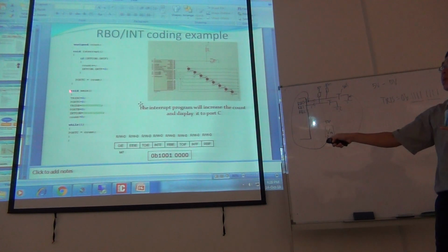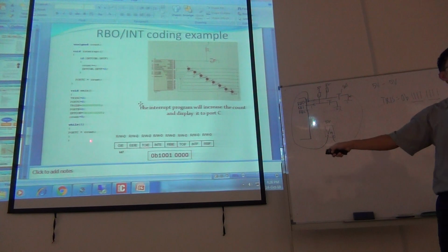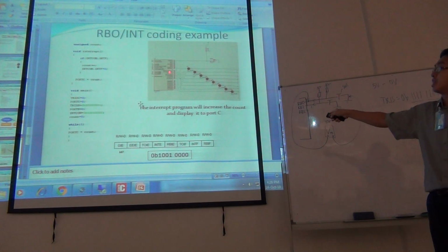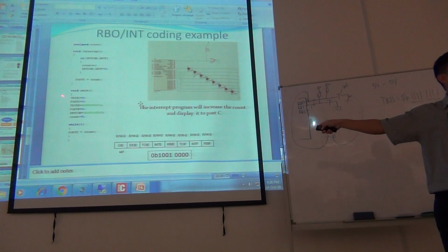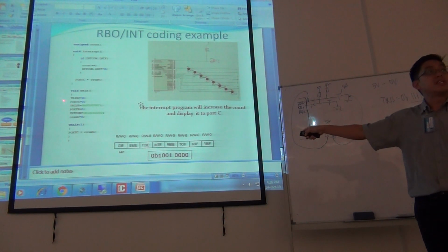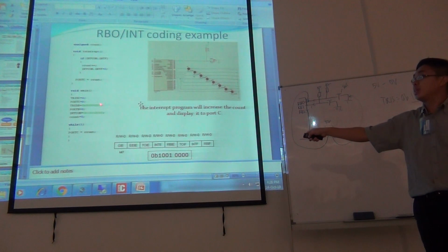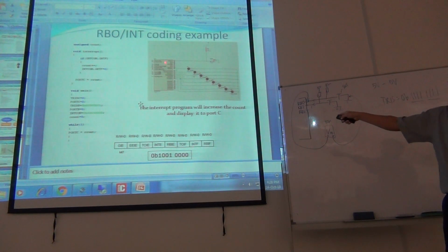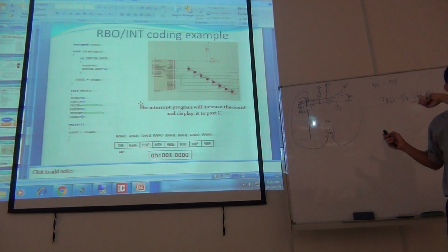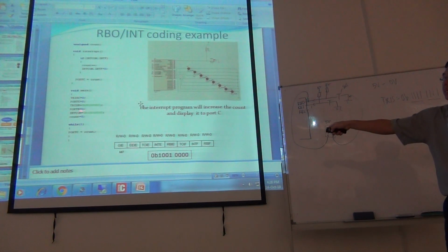Okay? Now look at your main program here. In my main program, I put TRISC all 0. 0 means all outputs for this port C. Port C now, I put all 0, going for 0 level. Now you look at TRISB. TRISB, only one as input, which is RB0. You know that interrupt must use this pin as the external input. Now PORTB is equal to 0, you can remove this one, it doesn't matter.